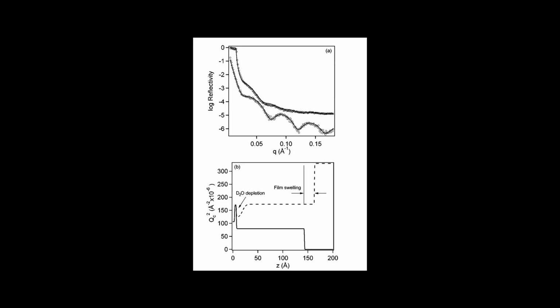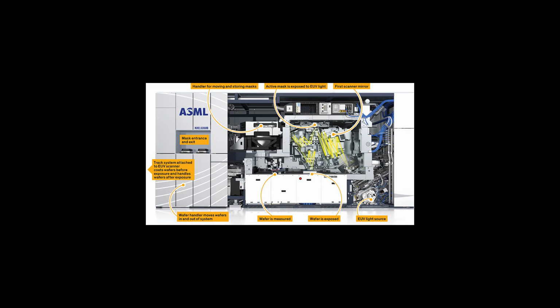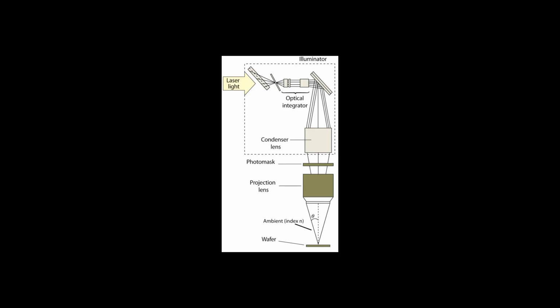Other areas where defects may be enhanced are at the wafer edge, where the water has to do an about-face reverse motion. It is important for the water not to pick up defects from the wafer backside. Generally, implementation into manufacturing is only considered when defect yields reach a mature level, e.g., comparable to dry lithography levels.